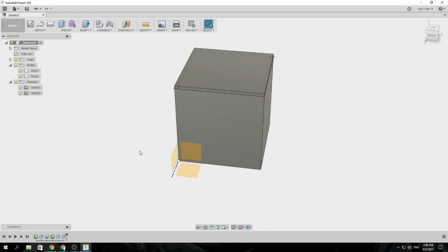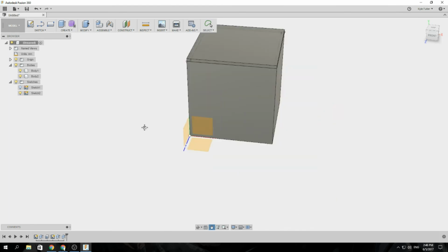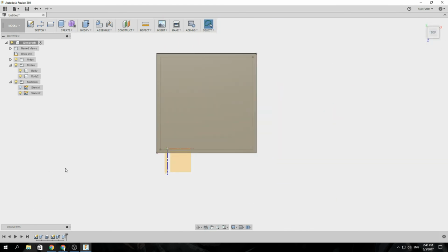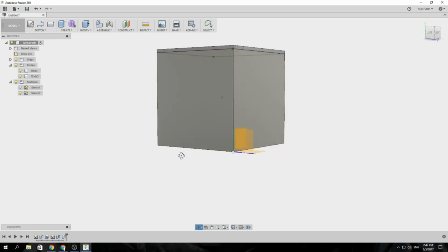When you do this, this is just panning. It'll only move things in 2 dimensions. But if you hold down the middle mouse button or scroll wheel, then to orbit, you hold down Shift and the middle mouse button.